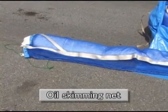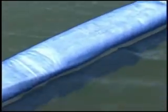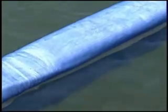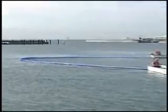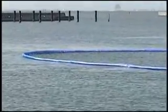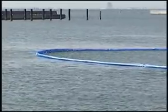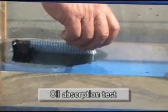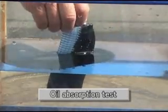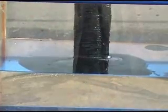Oil skimming nets contain sorbent in the net. The length of the underwater portion of the net is 30 centimeters. This allows seawater to flow under the net back into the open sea. The nets are light and not easily moved around by the waves. They are a very useful way to absorb and capture spilled oil. As you can see in this aquarium demonstration, as soon as the oil skimming net touches the oil, it starts absorbing and capturing it.